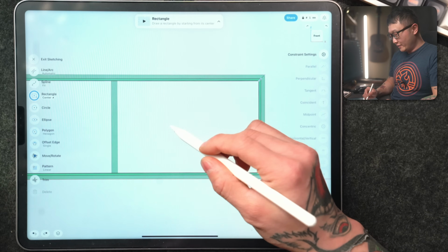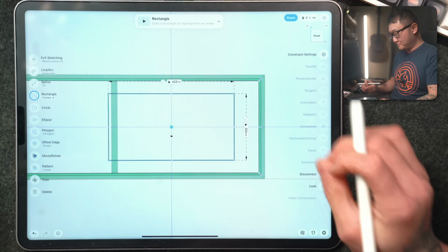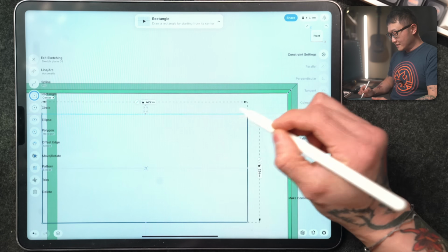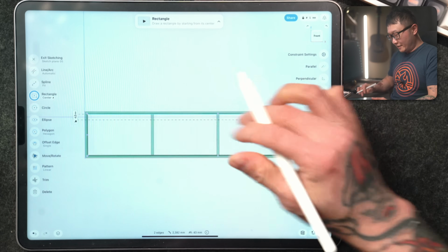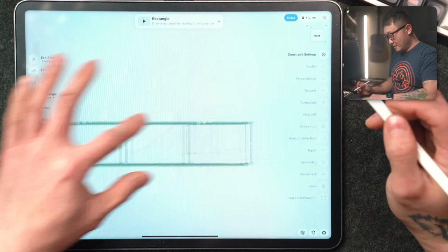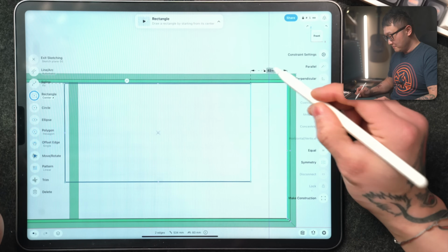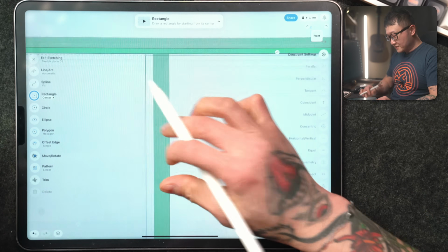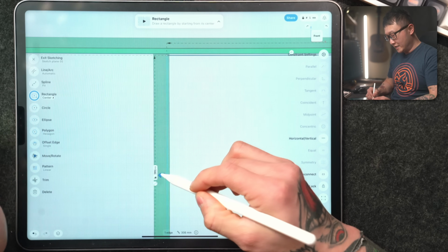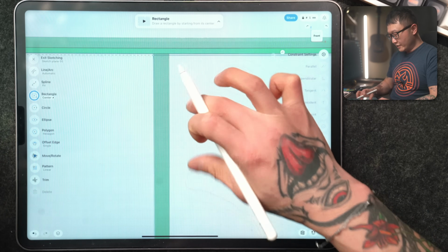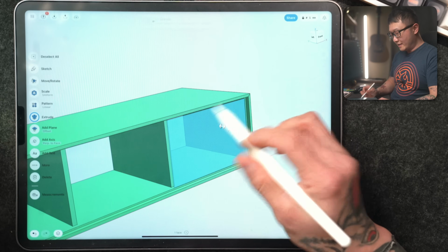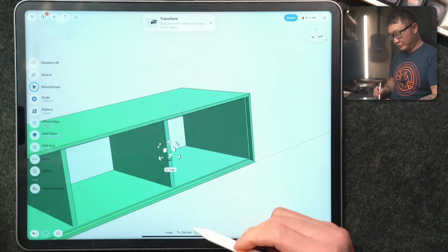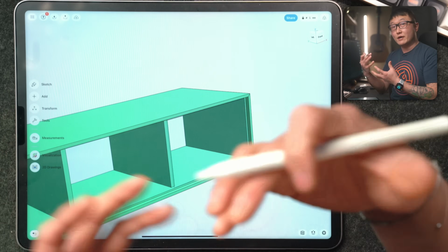Go to our rectangle tool and we're just gonna draw a random rectangle inside this empty space. Make sure that it's not snapping to any of the edges or points. Select this top edge and then the top edge of our opening, and we're gonna set that to 2 millimeters. And we're going to repeat the same thing on this right side and this bottom side. Okay, for this left side, we're just going to move it until it matches the edge on our partition. Somewhere like that. Okay, let's zoom out, and this is going to be the area that our 3 drawer fronts are going to occupy. And the total height of this is 306 millimeters. So divide that by 3, we get 102.